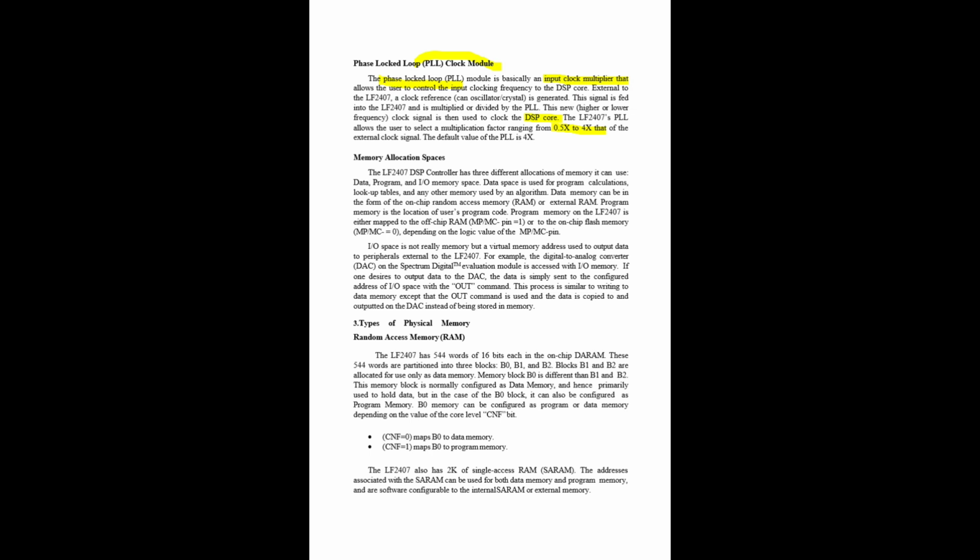That is why the 6 megahertz x is divided by 2, that means into 0.5. If the processor has to do operations at higher speed, then the same 6 megahertz x is multiplied by 4. So 6 into 4, 24 megahertz, is the frequency at which the processor is now going to work, so that the operation can be done quicker than the expected one.